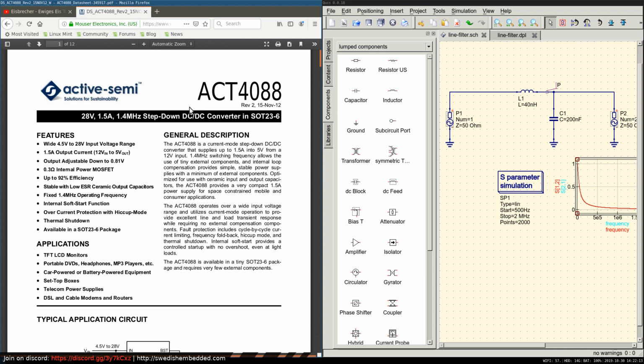And I think the net effect of that is something I've seen before, is that the buck converter can actually go into this unstable mode. So it will just sort of buzz, in a very high-pitched tone, and that can sometimes lead to circuit damage and all kinds of things. So we really don't want to have the impedance higher than 1/10 of the input impedance of the buck converter.